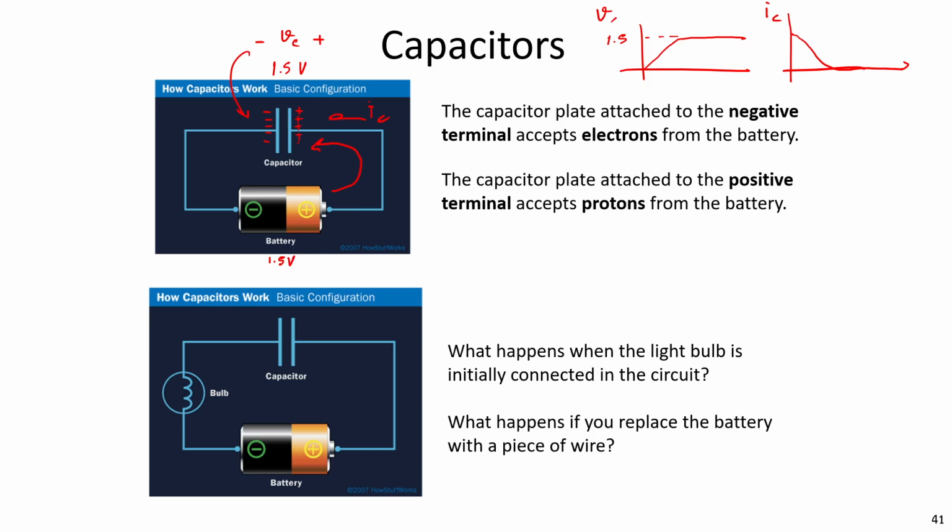If nothing changes, the capacitor becomes an open circuit, right? It's already fully charged. So if you connect this circuit, what happens to the lamp? The lamp will turn on at the beginning, right? After that, no current flows and it turns off, right? The lamp will turn on and then off.